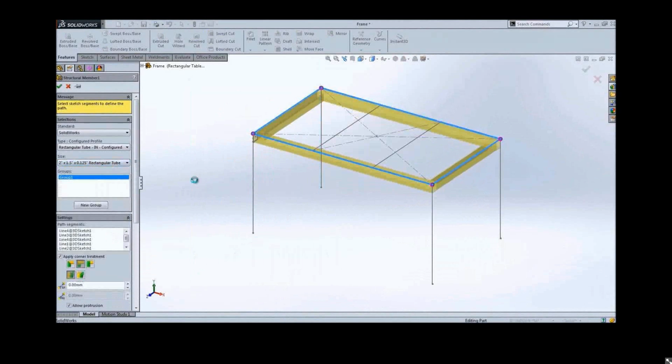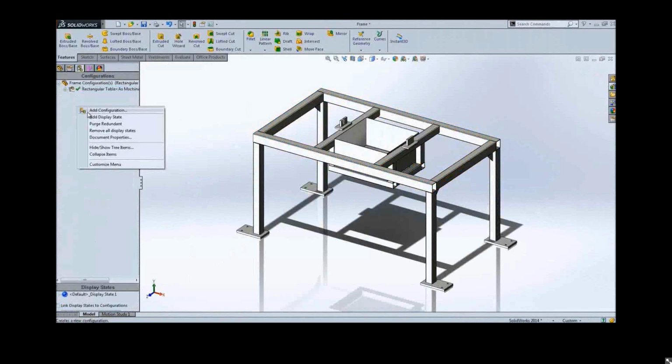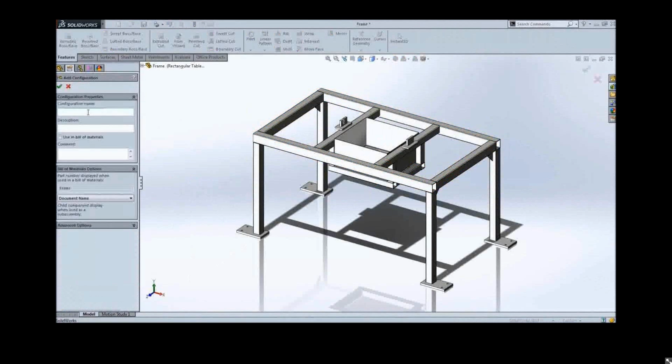And also, because all of these profiles are created not just from the same parts, but from the same sketch, you can very easily replace one profile with the next. So all the holes that go through it or any trimming that you did, that's all going to get updated very easily if you swap out the profiles because it's the exact same part file, just a different configuration. So it's going to be a lot easier to manage from multiple aspects.